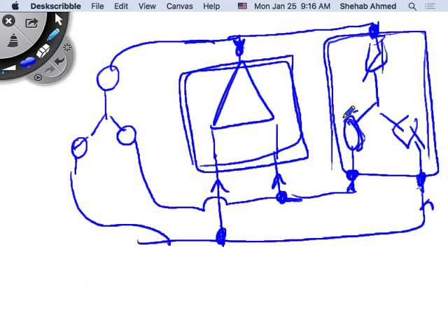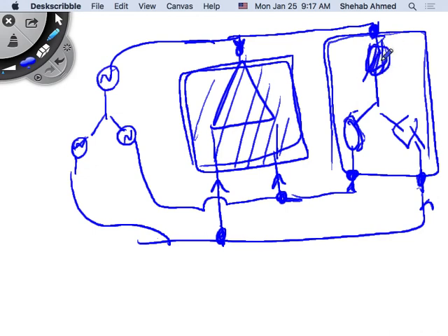So I can look at the voltages and the currents. For a star, I know the relationships very easily. I know how to take the star load and convert it to a delta. If you go through, there's some math in the textbook that is not going to be explained in the slides. But the idea behind the math is we find an equivalent star representation for the delta connected load. So I will deal with this as a black box that is consuming power, at a certain voltage and a certain phase angle for the currents coming in and the voltages applied. And I will say, okay, an equivalent star representation for this delta will look like a star, but it will have a certain impedance. This impedance will be different.